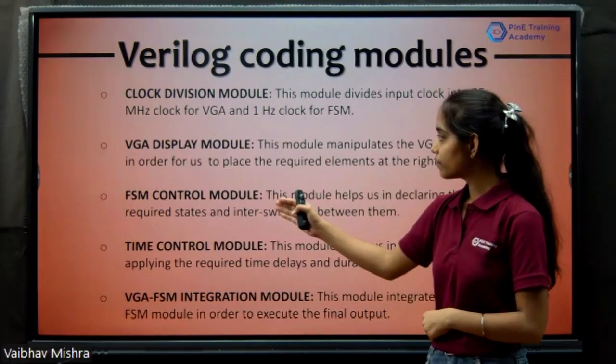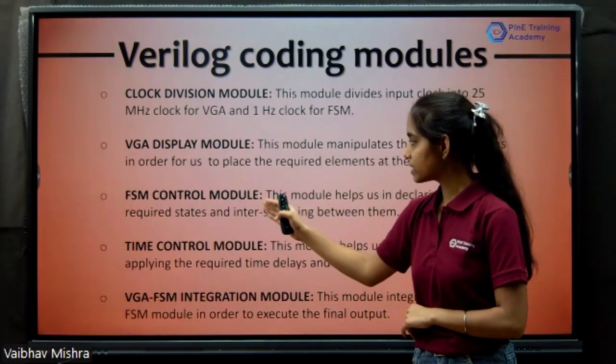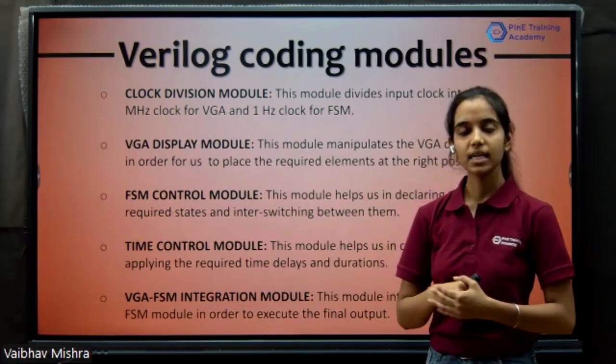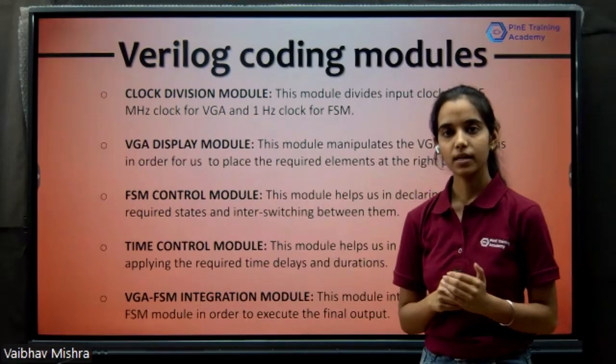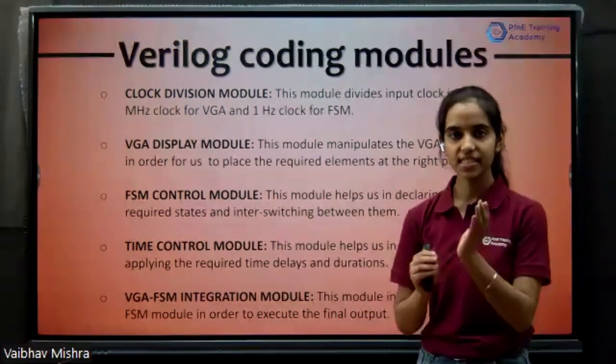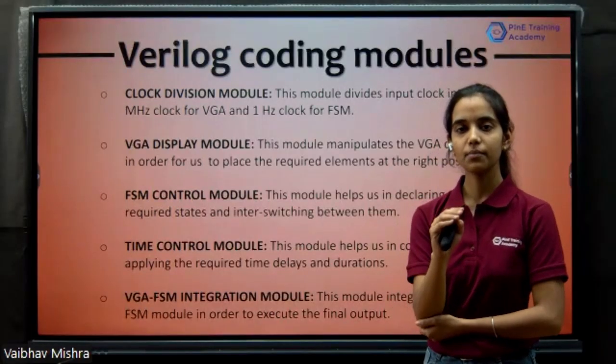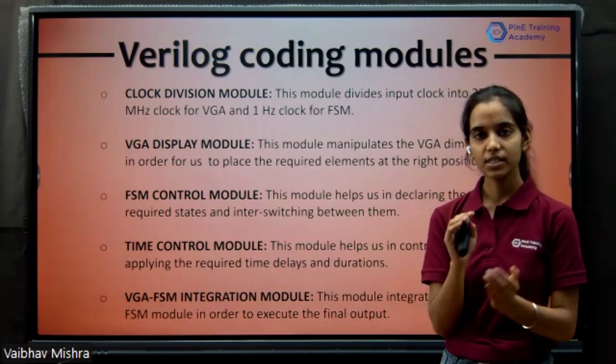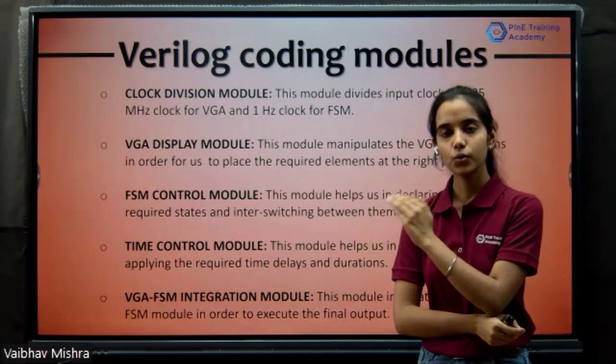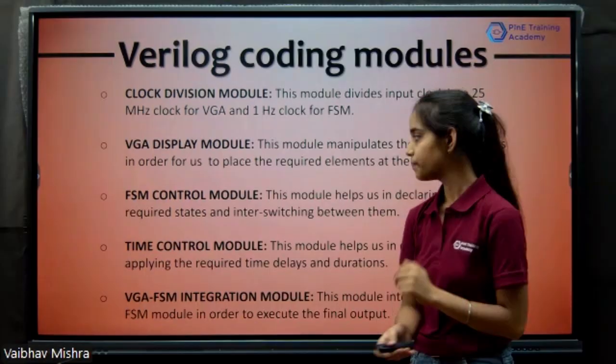The most important module is our FSM control module, which is basically a Verilog hard structure. It is hard coded to change the state transition from one state to another. We majorly used 8 states, which transition from green to red to yellow on each of the directions.